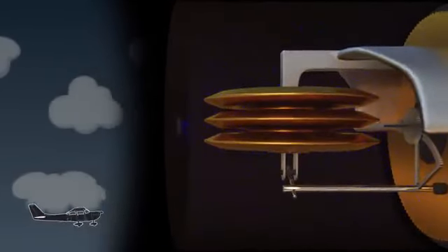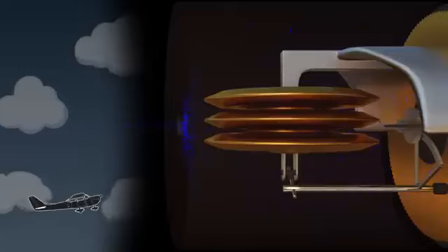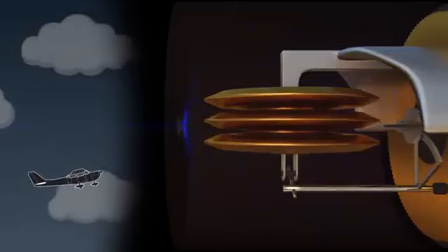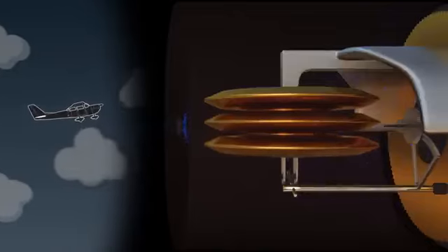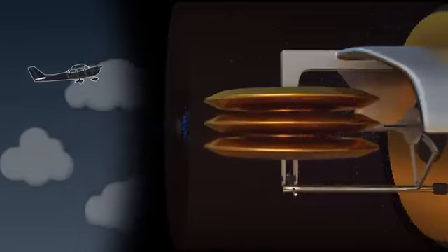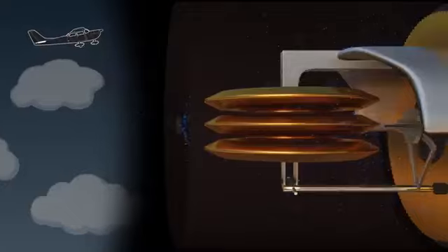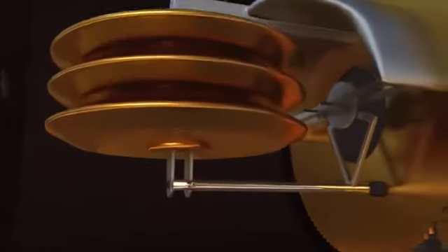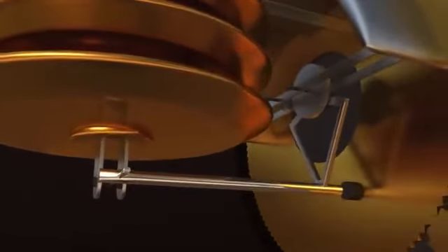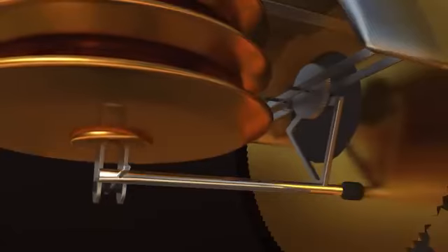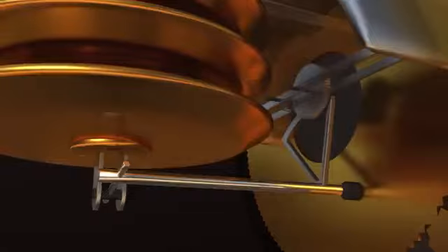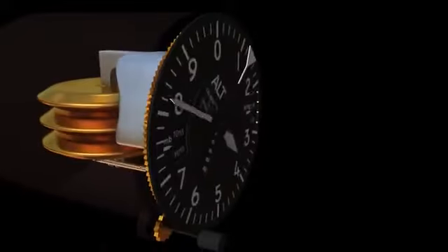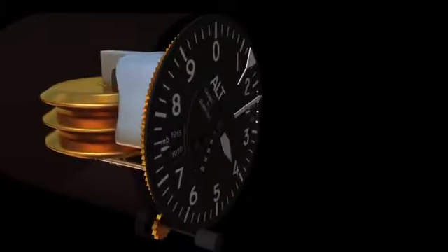As we increase altitude, the static pressure goes down. This means that the air inside the case will escape out the back and result in there being less air pressure in the case compared to the wafers. Because of this, the wafers will expand until both pressures are equal. Getting the wafers to result in an altitude readout is done through the series of gears, pinions, arms, and levers, also known as the mechanical linkages. These linkages will rotate the hands on the face of the instrument and show the airplane's altitude.